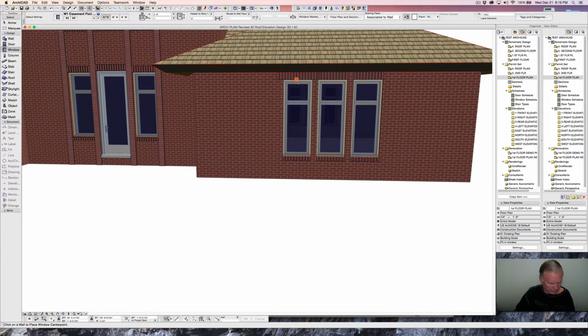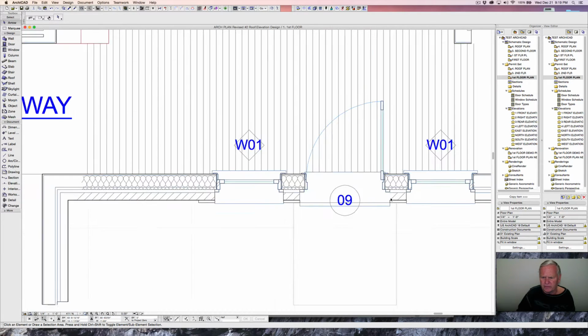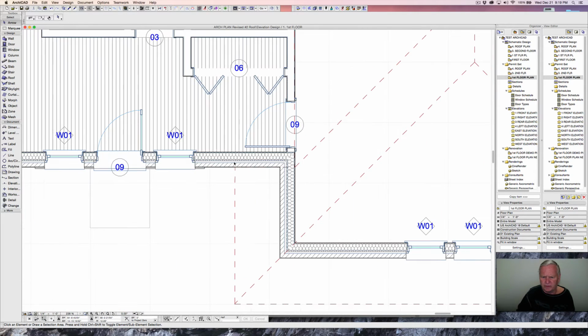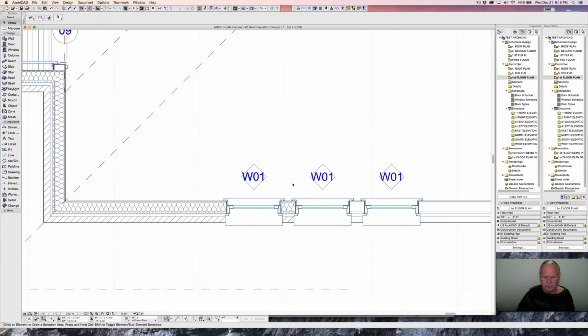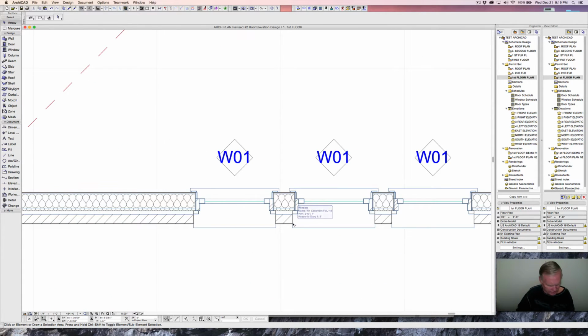And then we're going to suck up the settings and do that to this one, and we've got that correct. And now I'll bet, because these are overlapping like they are, that this isn't set for that 7 5/8. So back to the floor plan, zoom back out a little bit, come over to, trying to get to, all right, let's check this out. 6.5, what do you know? So we've got 1 1/8 inch, and I'll bet you it's the same for this side as well.